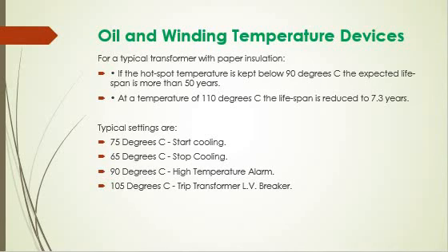Transformer applications usually include a guaranteed temperature rise at specific transformer loads. As an example, a transformer with a nameplate rating of, say, 17.5 MVA. Guaranteed maximum winding temperature rise of 55 degrees centigrade at 17.5 MVA. Guaranteed maximum winding temperature rise of 65 degrees centigrade at 19.6 MVA. The actual temperature of the winding insulation depends upon the ambient temperature. For an ambient temperature of 20 degrees centigrade, the maximum temperature of the winding at a load of 19.6 MVA will be 85 degrees centigrade.